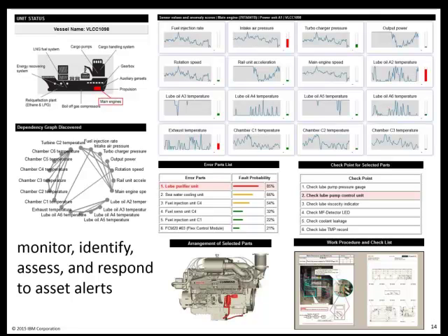You can see by the sensor values and anomaly scores, there's actually three measurements: exhaust temperature, intake air pressure, and lube oil P2 temperature that are signaling that there's an alert. Based upon this real-time analysis, we've developed the recommended error parts list, what might be the most likely problem here, and it's indicating the lube purifier unit. And then we also have recommendations checkpoint for selected parts.